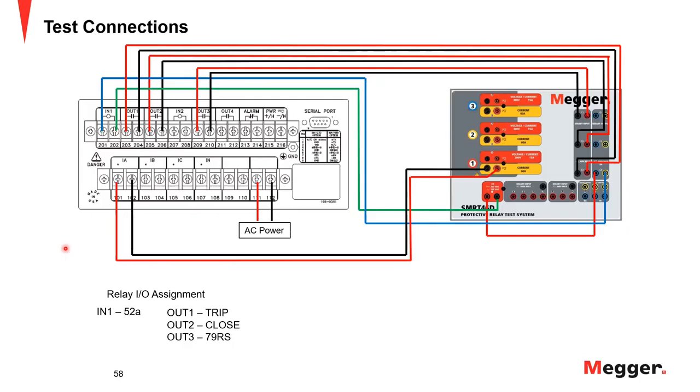Thanks. So while we have you, what is the difference between reclose and restrike? Reclose is when the reclosing relay tells the breaker or recloser to go closed, and it actually goes closed. If the fault is clear, then it's a successful reclose. If it is not clear, upon closing, upon a successful reclose of that breaker or recloser, the fault can restrike. So the difference in a reclose and a restrike, the reclose is talking about the breaker or recloser and the action that it's taking. The restrike is whether or not the arc actually reestablishes or not, whether the fault comes back.